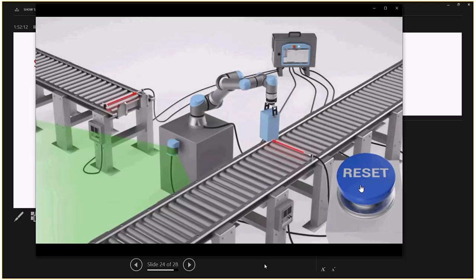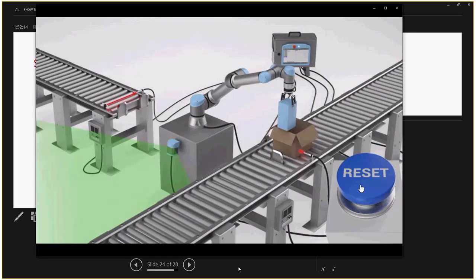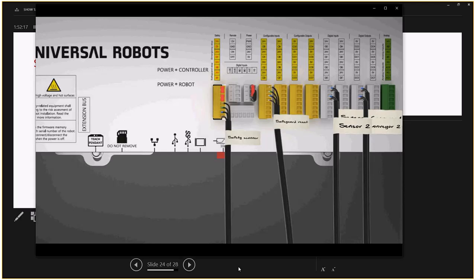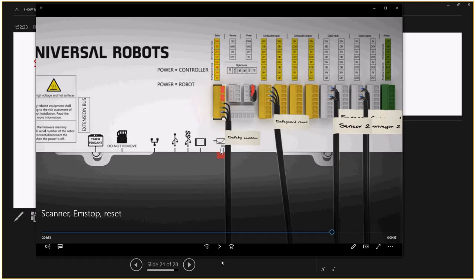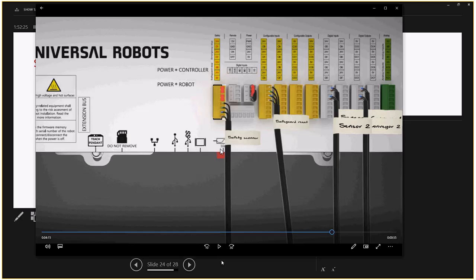This is just to make double assurance that nobody is still in there. Maybe somebody trips in that area and falls down, and then they need to get up, and their head gets out of the secure area, and before you know it, the machine starts running again, and when they stand up, their back will still be in it, and then they get hit. So it would be ideal to put a reset button on it.